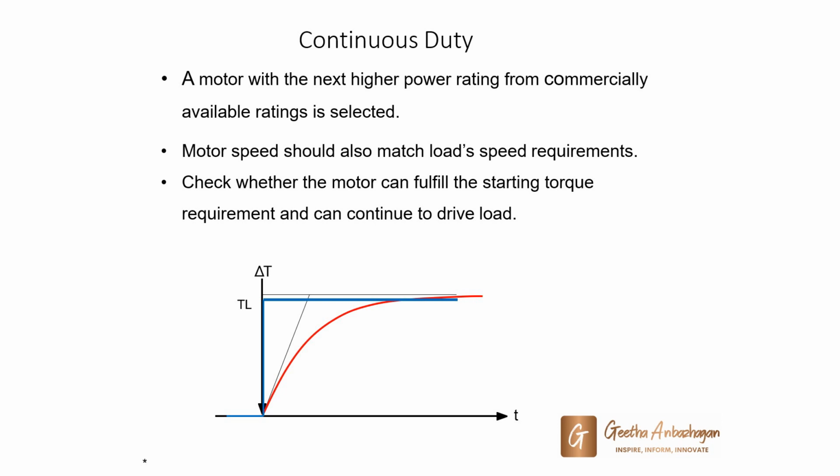The selection of motor capacity for such a drive is simple if we know approximately the constant power input required by the machine. In order to select a motor for a rating equal to the known power input requirement, one may be sure that this rating is the maximum permissible with respect to heating because the manufacturer designs and rates it so as to maintain maximum utilization of the material used at rated output.